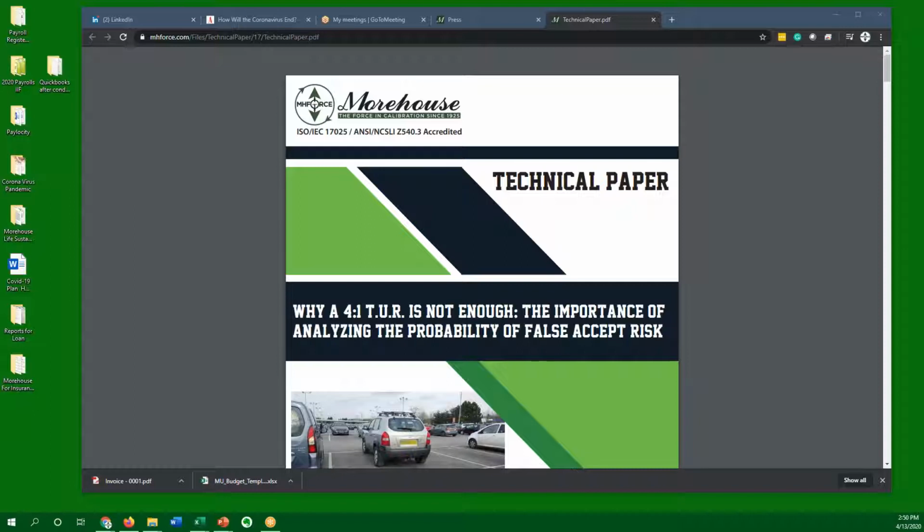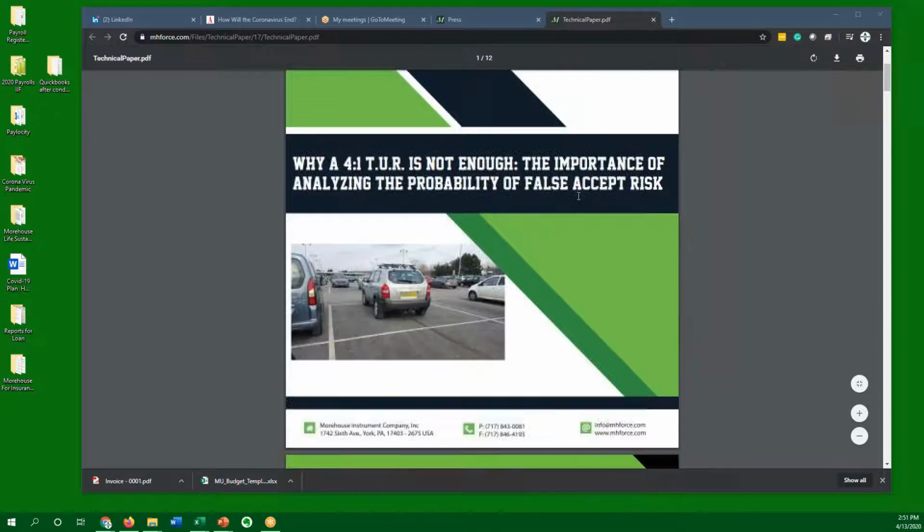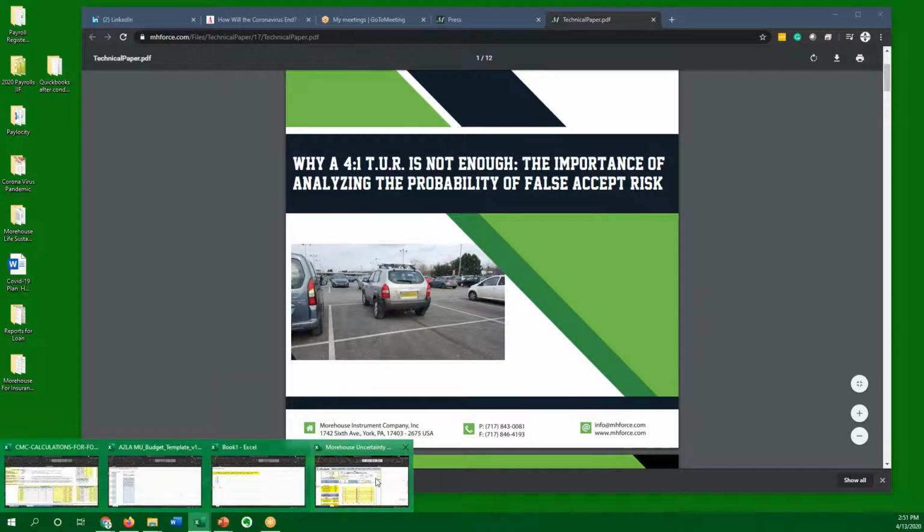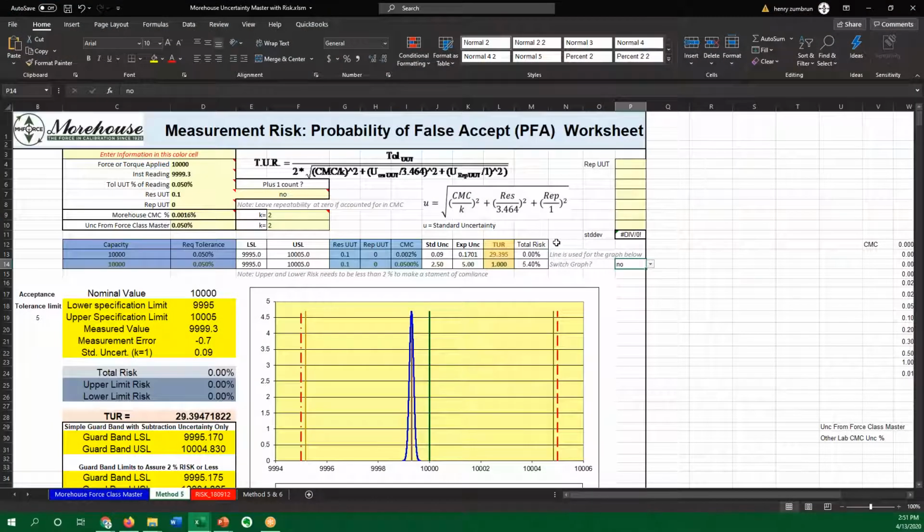This is a video introduction to our technical paper, "Why a 4-to-1 TUR Is Not Enough: The Importance of Analyzing the Probability of False Accept." I hope everybody has a chance to download this paper. What it talks about is TUR, and when we look at TUR, we're looking at tolerance divided by the calibration process uncertainty.